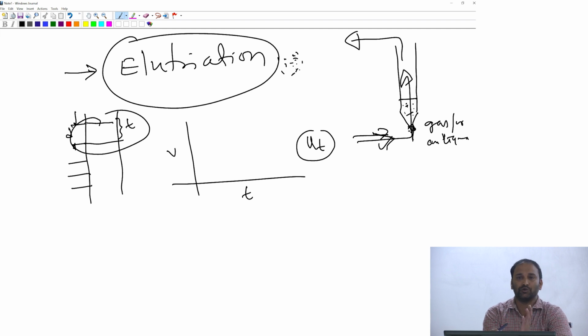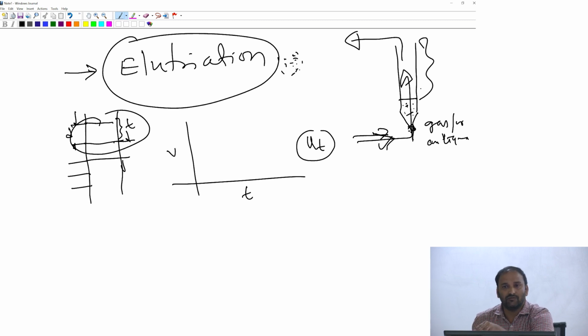One of the best ways to do this is to look at the velocity at successive intervals, and look at the instant at which the velocity between two successive regimes is constant. That's how people find the terminal velocity. I agree that initially there could be some case where the velocity is not the terminal velocity, but typically you work with a really large column. The fluid you're using for separation spends a reasonable amount of time there, the residence time is typically larger. In that time frame the particle does attain a terminal velocity, and your separation is based on whether the velocity of the fluid is larger or smaller than the terminal velocity of a given size.